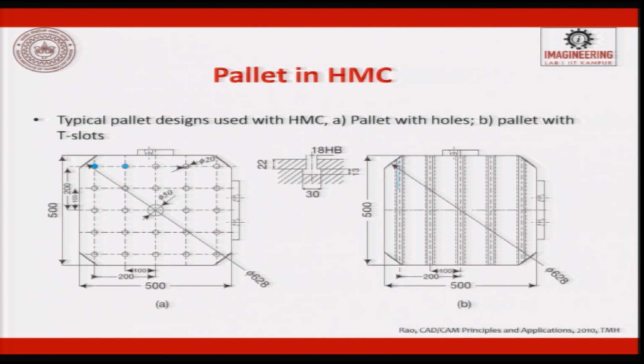So, correspondingly when you write a CNC program, you know the x, y and z coordinates of the workpieces very quickly. You can see here the diagonal distance is 628, the length is 500, and between pin to pin it is 100. So, it is like a matrix, several dots equidistant. So, this is predominantly used for locating some complex jobs, and here these points are discrete.